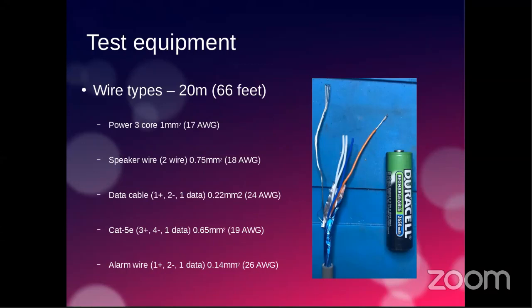Unterminated wires are a real problem because on unterminated wires, the signal reflects, and that will generate noise in the data signal. Yep. So how does power injection affect this with several injection points? So power injection doesn't change the data signal. The power injection can lower the ground though. And so it can,